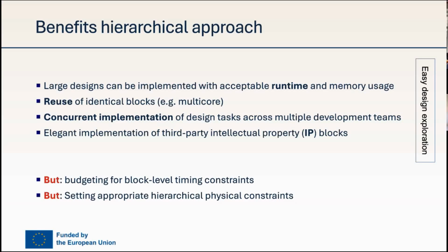The first one is that we require a careful budgeting of the different blocks, especially in terms of timing constraints. And second, that we also have to define very precisely the physical constraints for the different hierarchical parts. In the domain of 2D, we have some tools which are helping us in this regard, but again, in 3D, there is almost no tool for doing this.